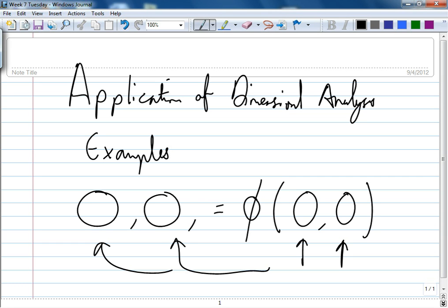So today, the two things we'll do. We'll do problems where it's maybe a unique problem, so you don't know what it is in the full scale. Instead of building the bridge first, you build a model and test it. A bridge is a complex problem, so there's no standard one. Number two is if there are standard problems, like flow past a cylinder, then most likely someone already did it. They plot the graph, and then we just apply that graph. So there are two applications here. That's why I brought my textbook also, all the graphs are in there.